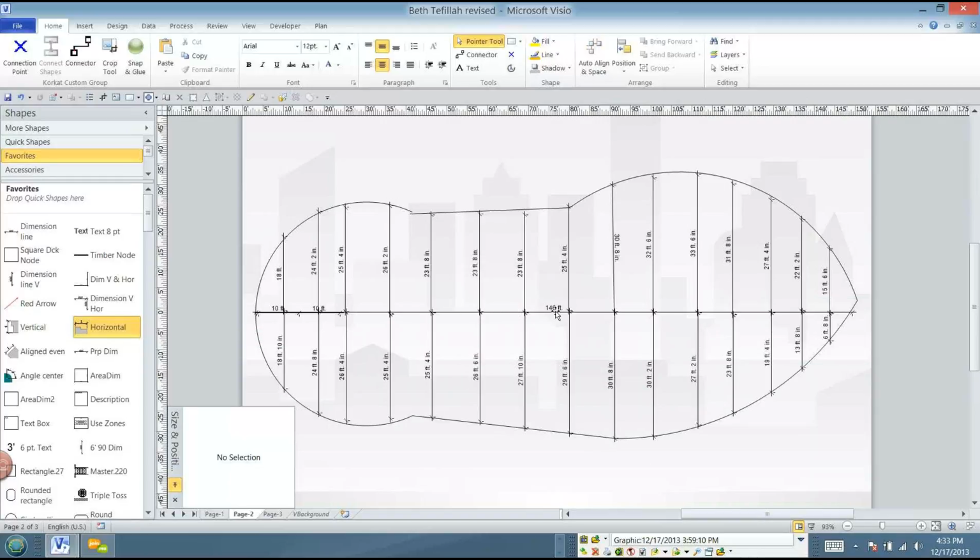So this is obviously bigger than you usually find, but the shape that's been scaled is 146 feet from one side to another. So you plant your tape here and you run it all the way over here. And I didn't set the increments here, but pick an increment that you think is good based on the scale of what you have. Okay. So in this case, it's easy to do 5-foot or 10-foot increments. So let's say you go every 10 feet, you plant a flag. 10 feet, plant a flag, 10 feet. So this goes 10 feet, 20 foot, 30 foot, 40 feet, all the way across.